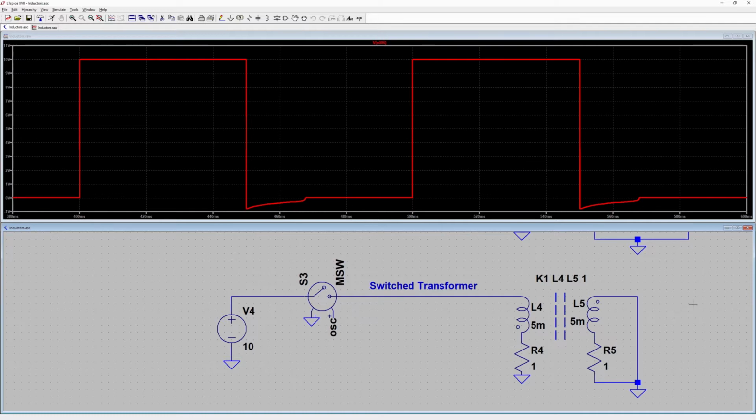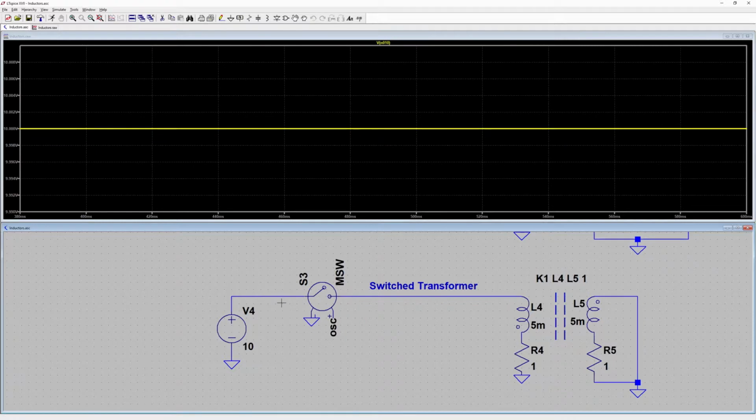Ask your mother. When two inductors are placed such that the magnetic flux from one inductor also flows through another inductor, a transformer is created. A transformer is sometimes more accurately described as coupled inductors. A transformer does not have a direct connection from one winding, or inductor, to the other. There is only the magnetic flux and parasitic capacitance linking the primary and secondary windings of a transformer, assuming that something hasn't gone horribly wrong. Let's use ideal inductors and an ideal core for our discussion, which operates under the assumption that 100% of the magnetic flux from one inductor passes through the other inductor as well.